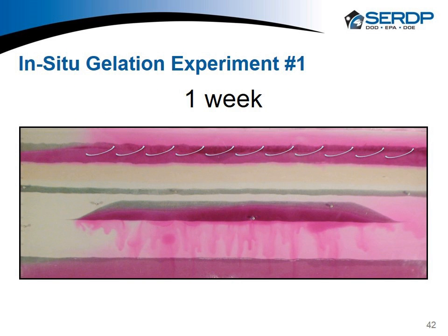After 1 week we see quite vigorous mixing under the coarse lens, and the underlying coarse layer was invaded with the dense solutions. At the top there is a little bit of diffusion into the clay layer, but most of the dye solutions are moving upwards due to the interaction with the background flow. By the way, background flow is from the left-hand side to the right-hand side.